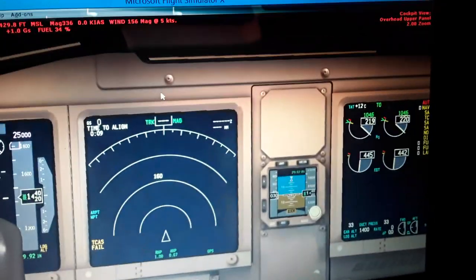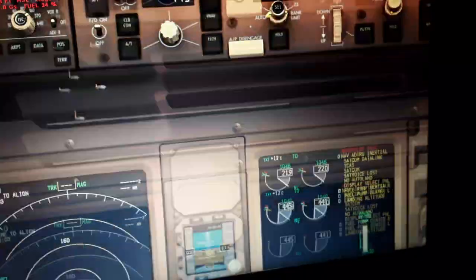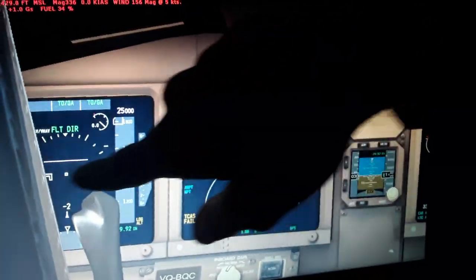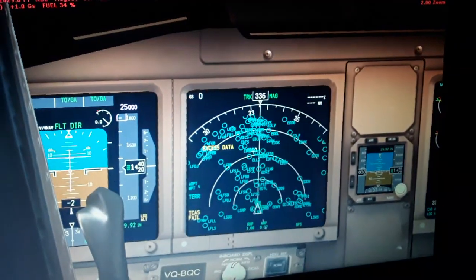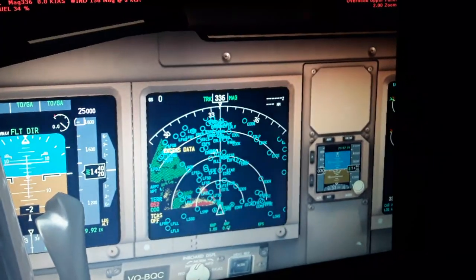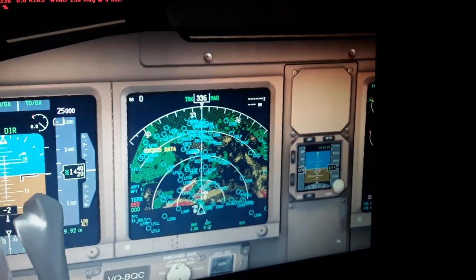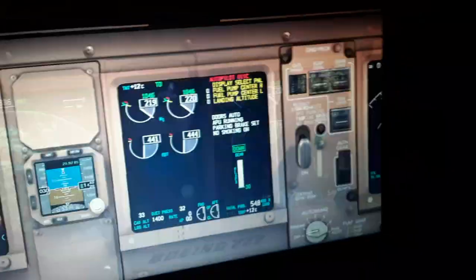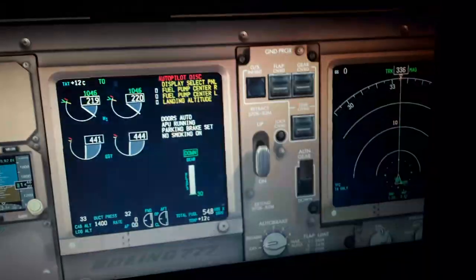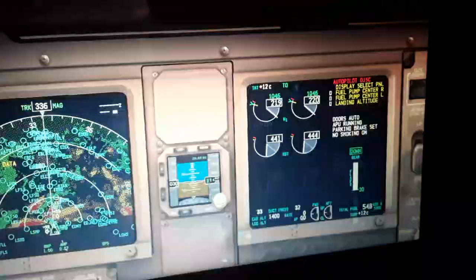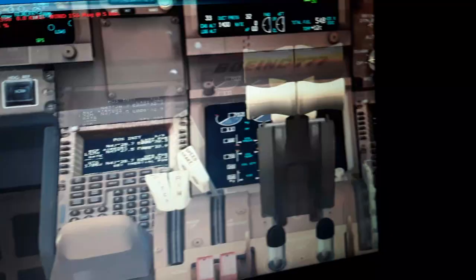So this is what it's actually doing. This switch over here, we have the display of the GPS position, the terrain, the airports, the barometric altitude, the gyroscopic precession, all the data here displayed, the airspeed and the angle of attack of the aircraft as it flies. So here we are, it displays in all this and also supplies to the flight management computer and the autopilot and auto thrust and the FAREX.